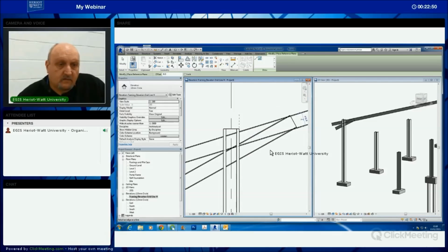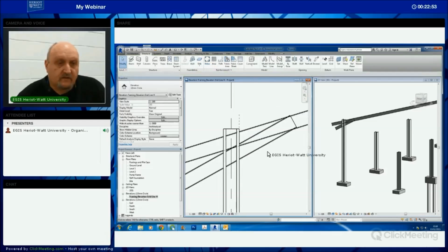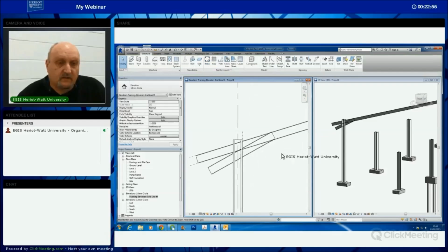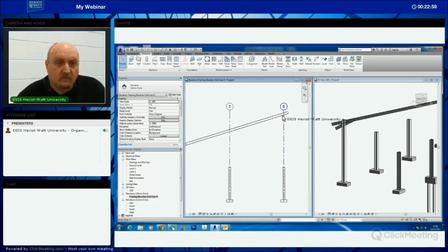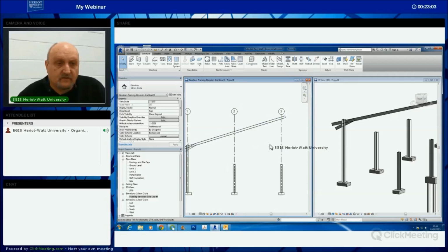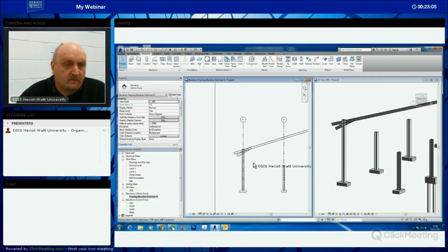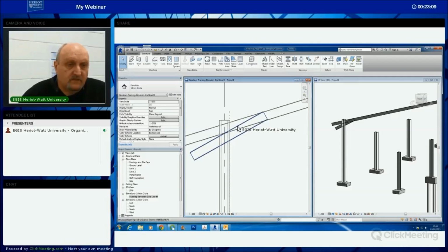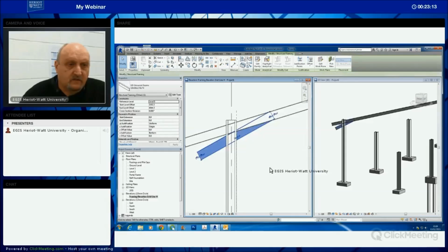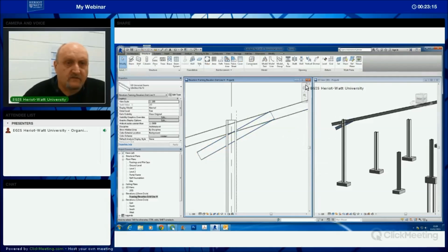Alright, I'll trim this down a wee bit. So I've finished with the reference planes. I'll put one in a minute on the middle grid line 3. I'm going to give it an offset. In other words, I want to stop this before it reaches the middle of this portal frame. But still working on this corner with this haunch, I'm going to trim this down using these reference planes. So I select the object, just have a wee look, and that's fine.